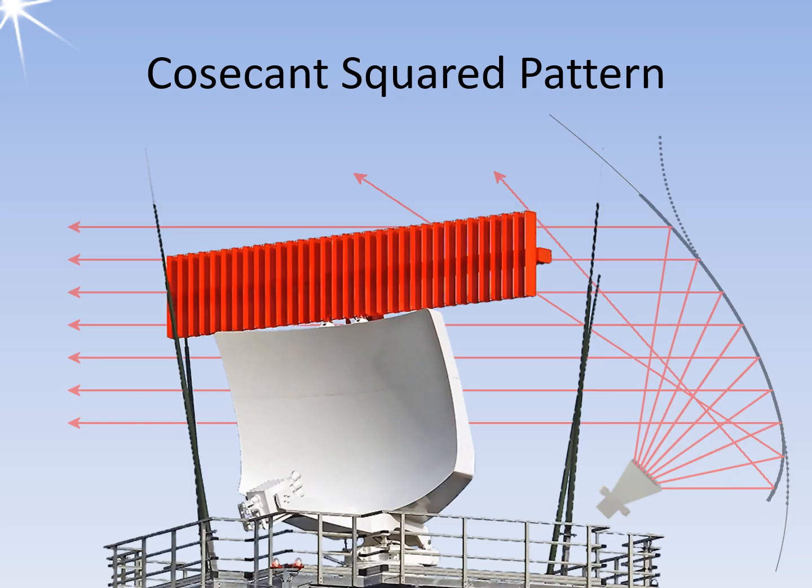This inward bending can be clearly seen in the antenna of the ASR/NG terminal area radar from Hensoldt. The red antenna above the parabolic reflector is part of the monopulse secondary surveillance radar, abbreviated to MSSR. The four rods around the antenna are for lightning protection.